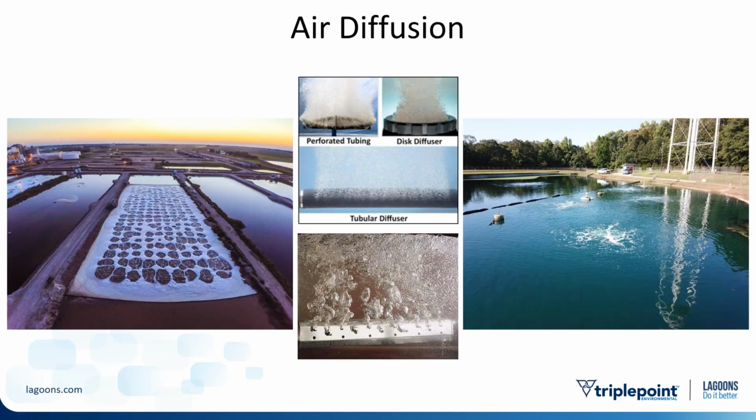There's air diffusion. The idea is we're putting air in at the bottom and letting it bubble up to the top, creating oxygen transfer. And there's fine bubble aeration, creating a lot of surface area, versus coarse bubble aeration, very little, at least comparatively, surface area. But the idea is release from the bottom, bubbles to the top, kind of a fizzy action.